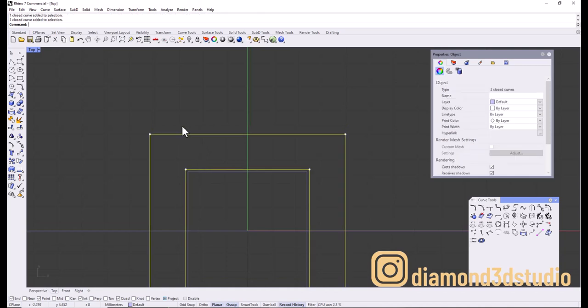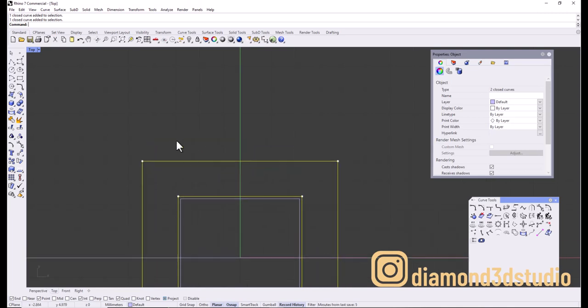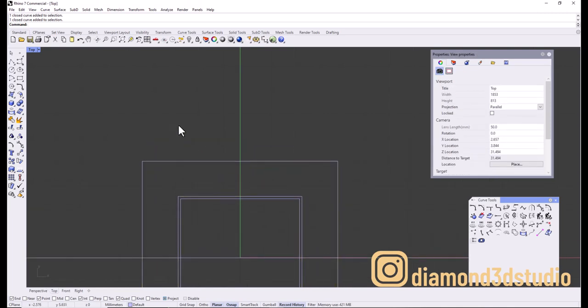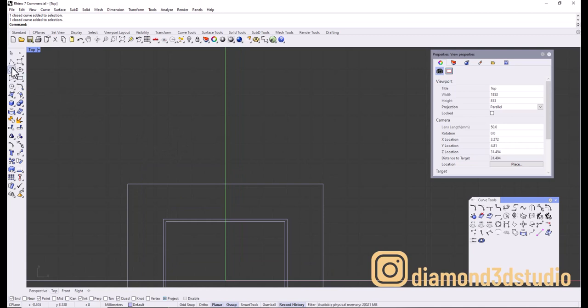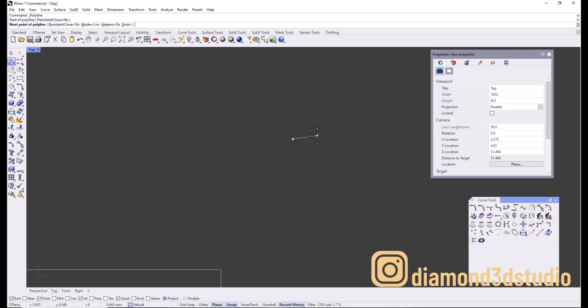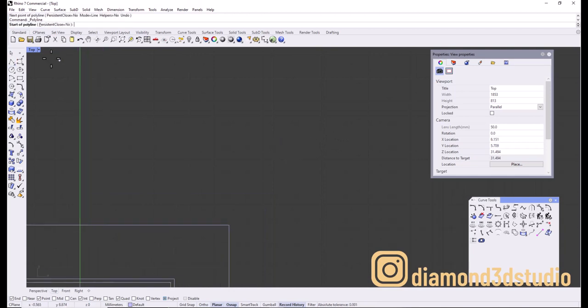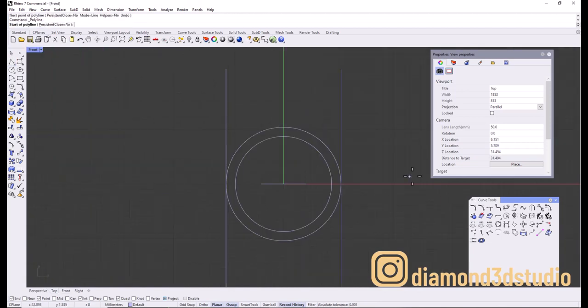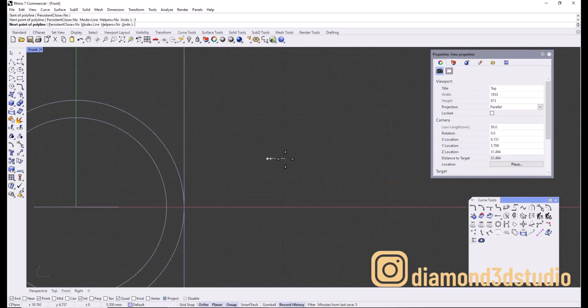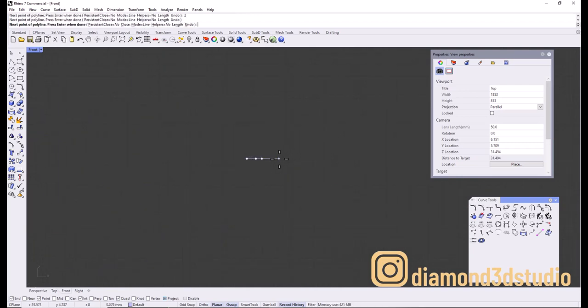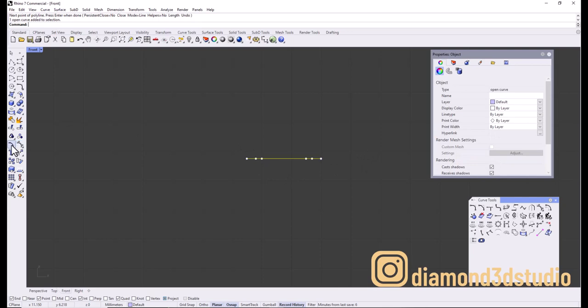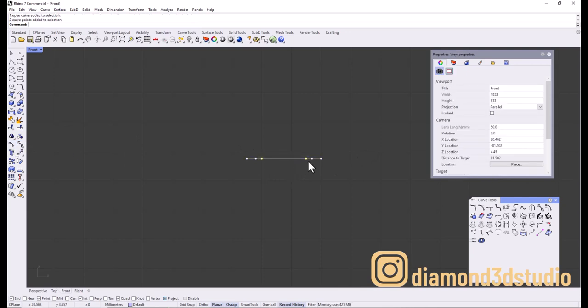Now when you do an offset, there are some parameters we have to take care of. For example, if you're doing a pavé on computer, a pavé which has a border on the sides, I normally keep it around 0.3 to 0.2 for the depth, and the diamond size, let's take it as 1.5, and then 0.2 again, and 0.3 again, right? So yeah, we have the points already here.